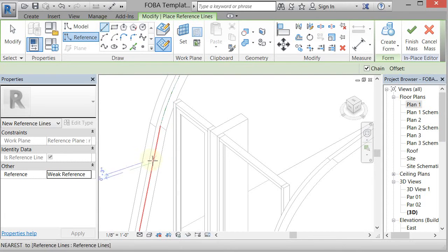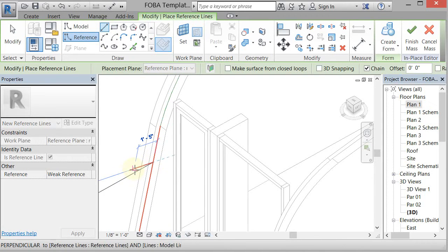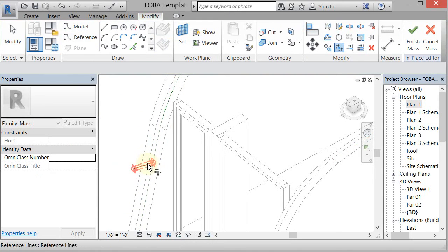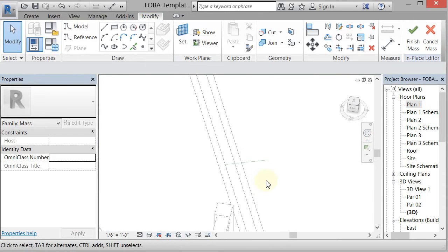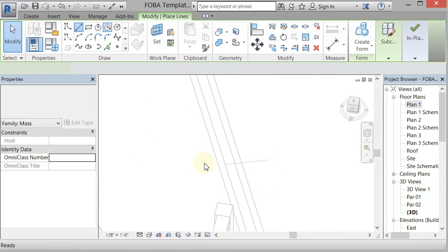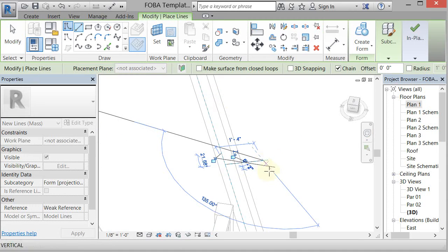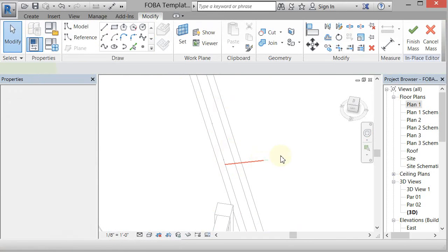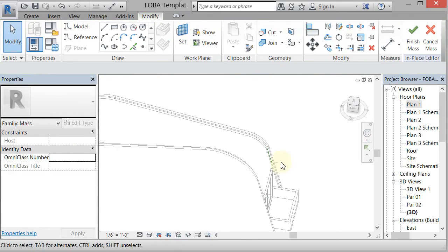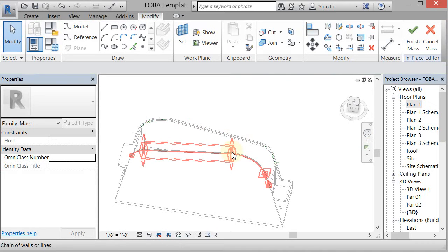And then I'll do the same process. So I'll make a line, goes from there to there. I'm going to invoke the trim command using the shortcut, which is TR, and trim that guy off. Tab select and get rid of that one line that I just made, and do the same thing over here. So drawing a line from there to there, TR for trim, pick that, and then delete that line that I just made. So now what I've got is that and that, right?